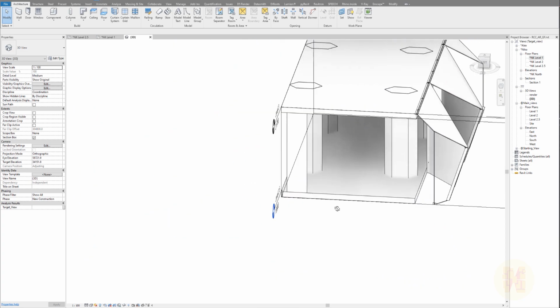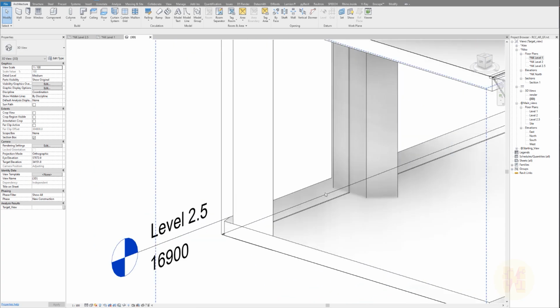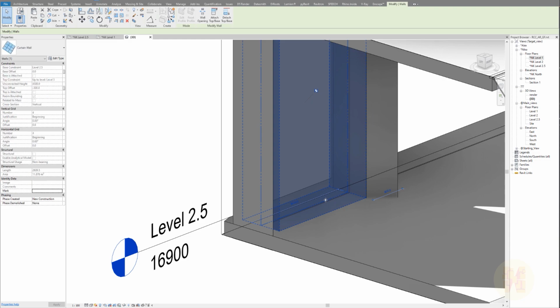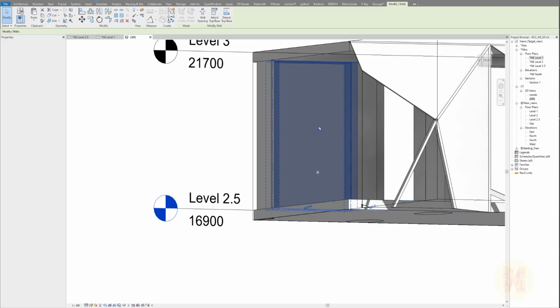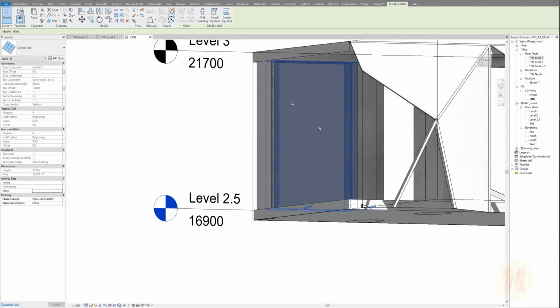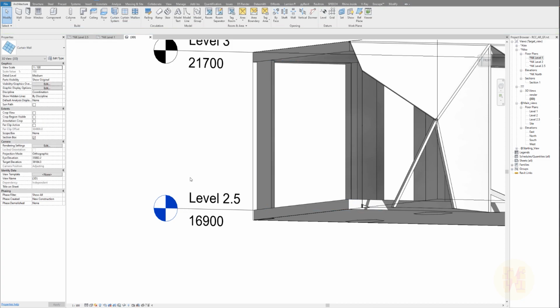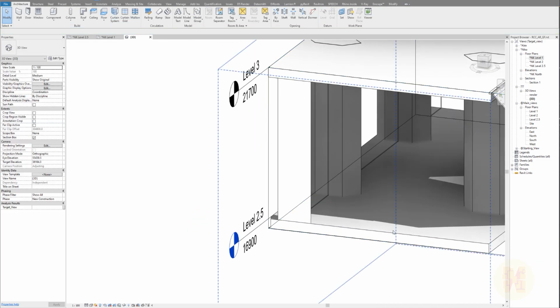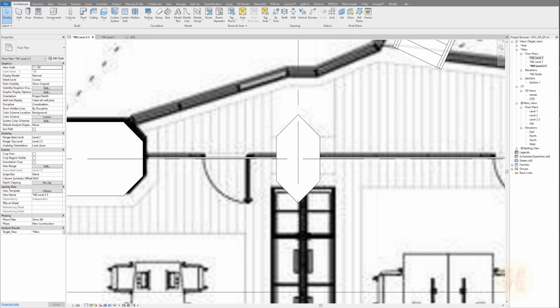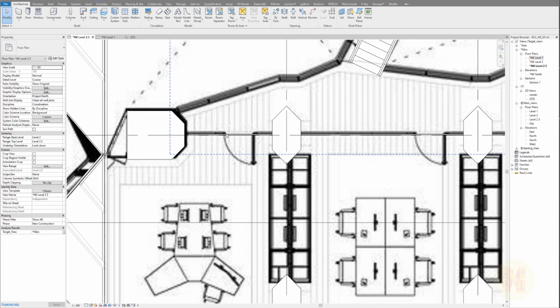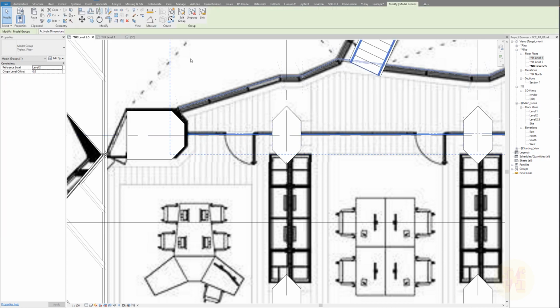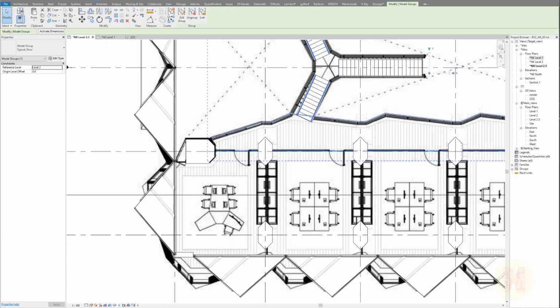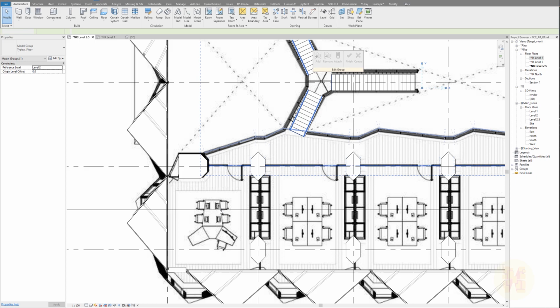So we will draw a wall between offices, and we will change our storefront, because right now, as you can see, our storefront has no door and no mullions. This is not what we want. We want to create the real model. So I think it's better to start from this storefront. As you can see, this storefront is inside a group. Let me select it, and I will go to edit group.